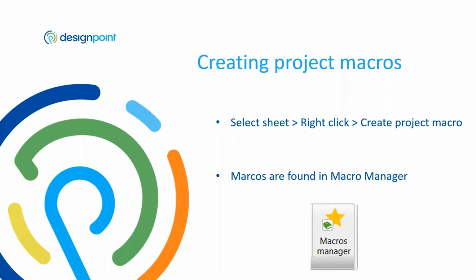In a lot of the project lines with our customers, they may have a particular schematic project that they're using and they want to use one of their sheets over and over again. Maybe it's something that they reuse over and over in their electrical design. And instead of showing just a section of that, they want to show the actual sheet. That's a project macro, because that's in the project, okay? And then we can also manage our macros from our macro manager. You want to look for your macro manager symbol.